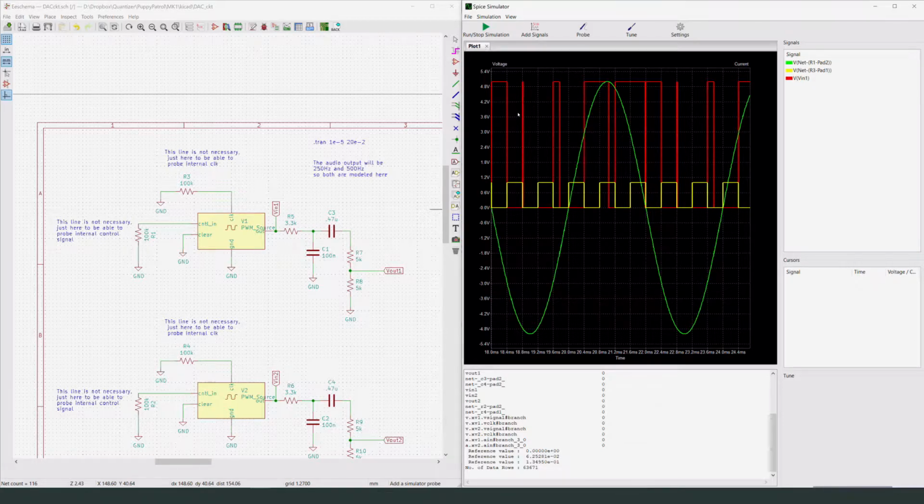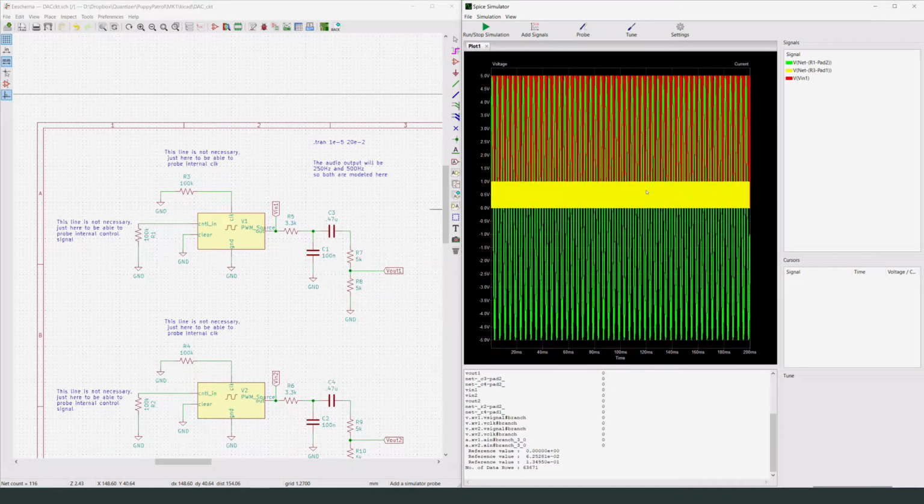And then it's going to keep doing that, and you'll see how, depending on where you're at, we have this pulse width being modulated by the voltage value of our input signal. And so if we just change the frequency of this, we will get a different pulse width modulated output. And that's how we built that circuit. So, you know, it works, and you can use it, so you don't have to go through what we did, which was to create it ourselves, because there was not a simple block to do that.